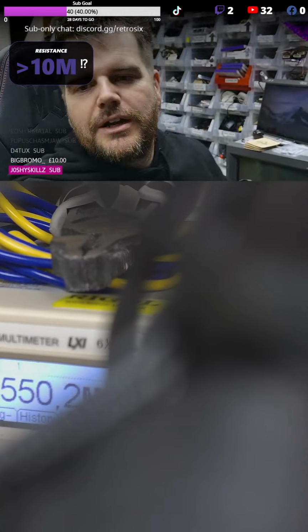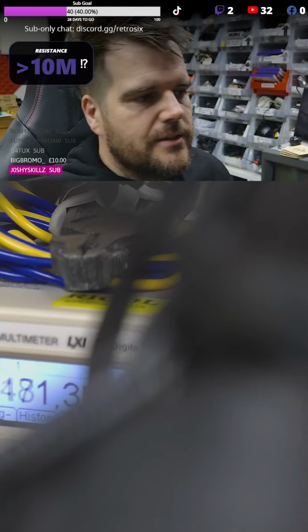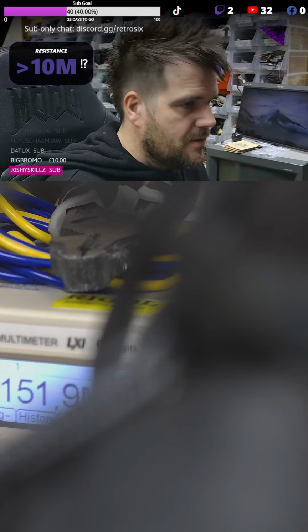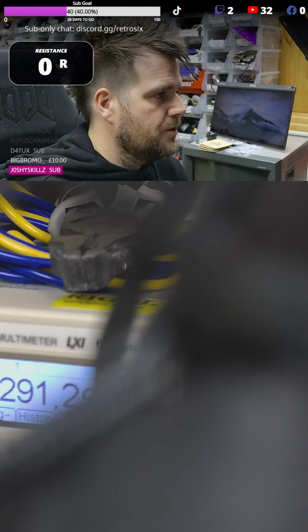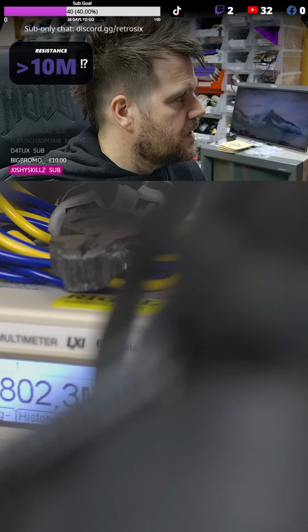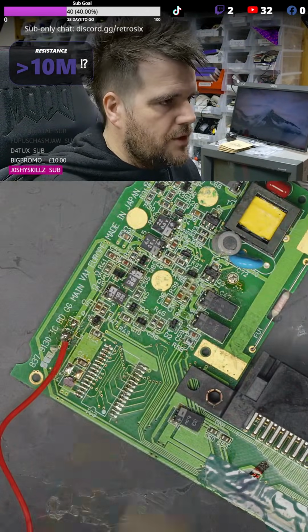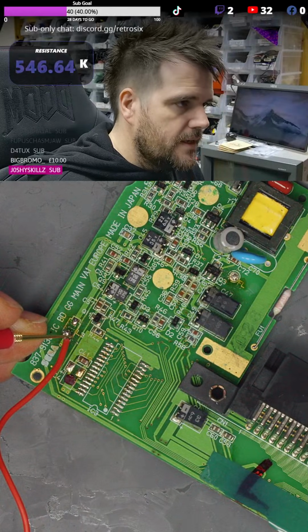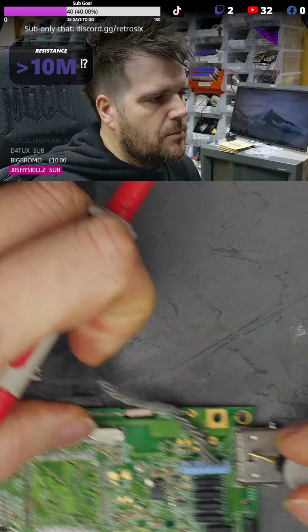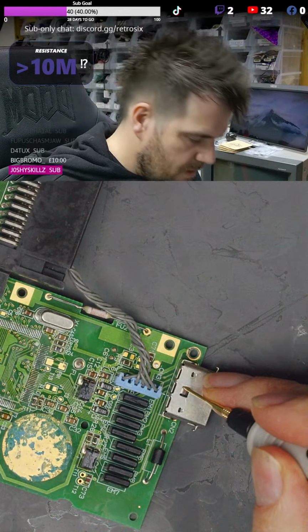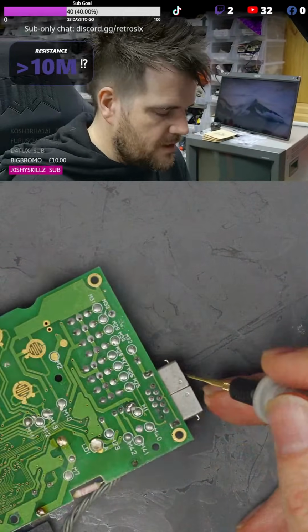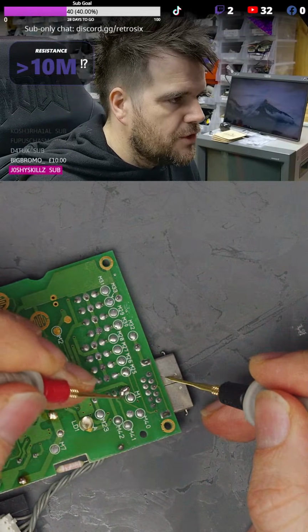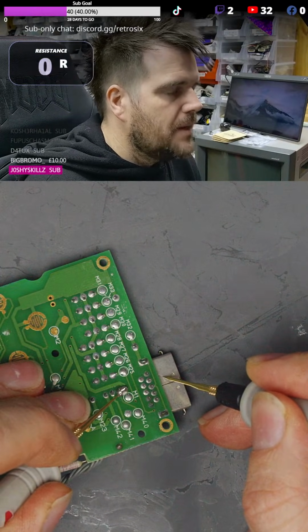I'll update the software, because obviously I've written this software, so now I can at least write it so you can have a high accuracy mode. But if I go onto there, see 0.29 ohms. So where I'm probing, I'm basically going on ground and on here. Now the theory is, if I probe closer to where the short is, so I come around and probe on the point we know the short is, that's the perfect example. Let's probe on the pad here.